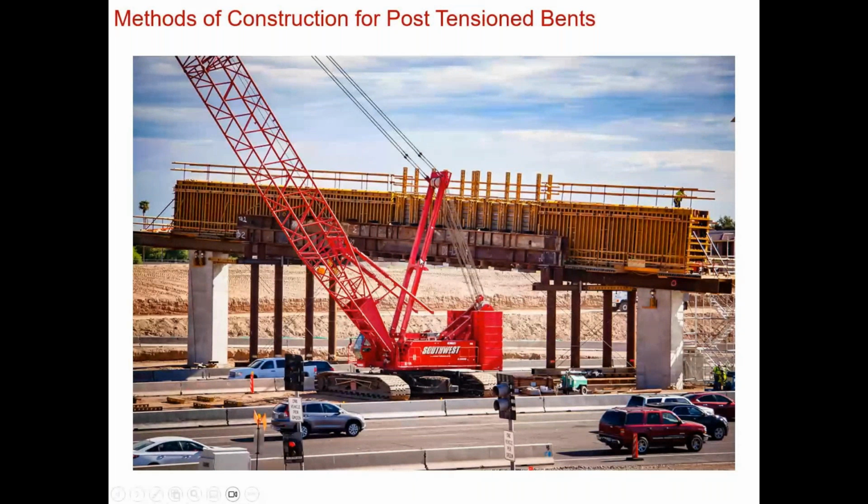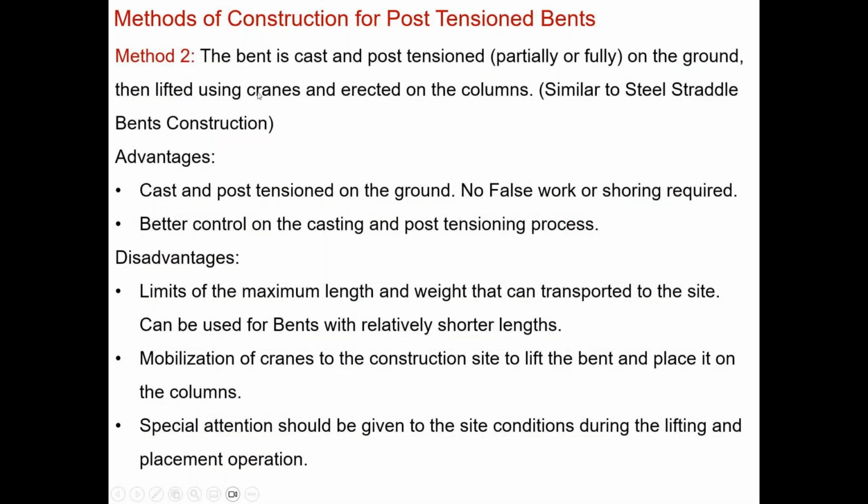The other method is if the bent can be cast and post-tensioned on the ground, which is also one of the good methods to build those types of bents. And of course, when I say post-tension, it can be partial or full. It depends on the design and how many tendons can be tensioned when the bent is only seeing its self-weight. Most of the time it's very difficult to fully tension all the tendons in the bent while on the ground. This can end up with quite high stresses in the transfer stage and crack the member at the top, so it's not really a good way to do it.